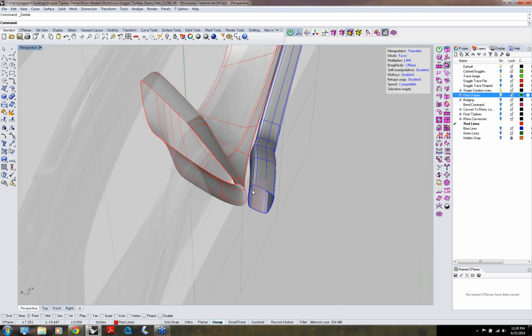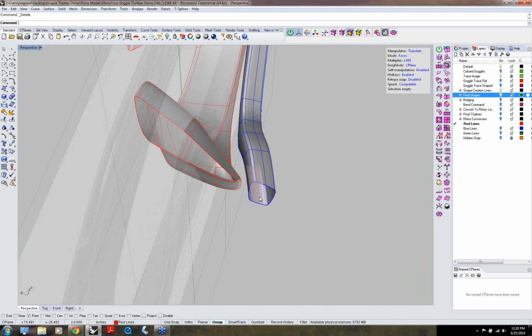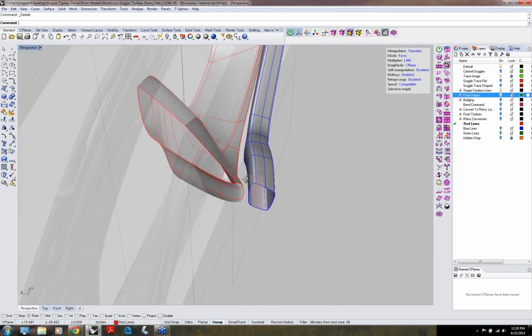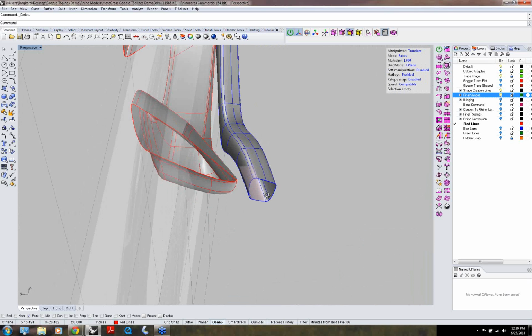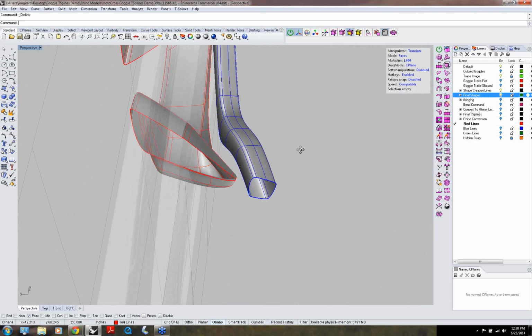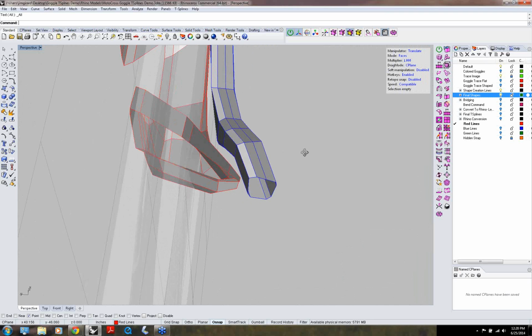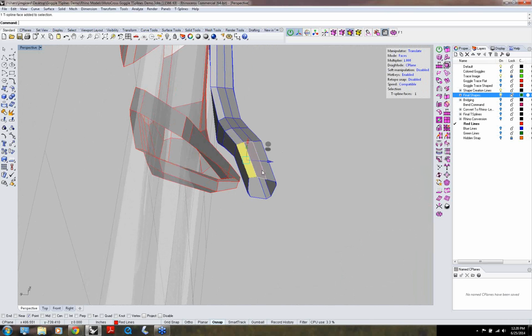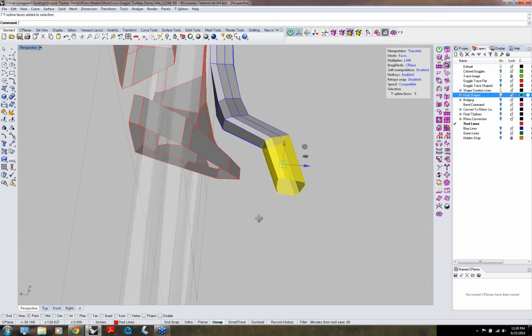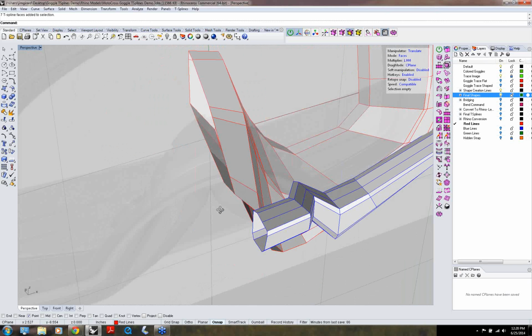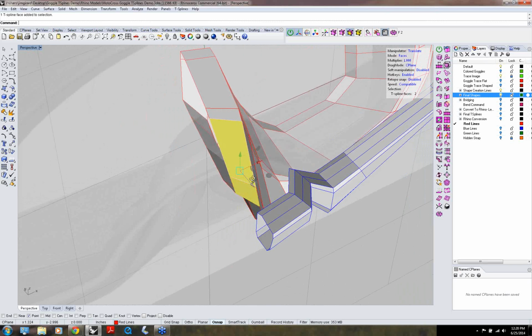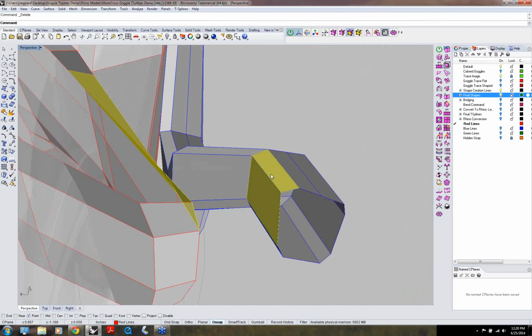And one of the things that took me a while to get used to is, as I've modeled in solid programs like SolidDesigner from Hewlett-Packard or Rhino, once you've modeled something, it's sort of there. But that's not the case with T-Splines, in that they have what's called the box mode, and I just come over and say pick some faces, say loop them, and move them out of the way so that I can get into where I want to work. And I'll pick that face and this face and this face and delete it.